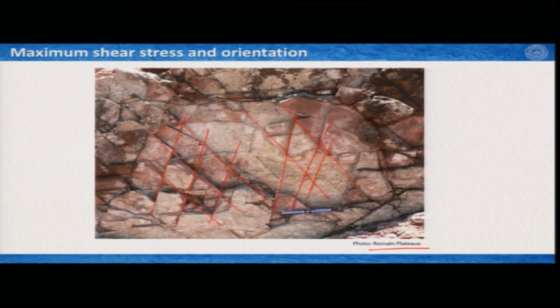Now, it is wise to imagine that these intersection lines, because these are planes, is one of your principal axes of stress, and therefore, if I consider this, these two are your other principal axes of stress. So, I do not know which one it is, but if I consider this one which is projecting upward from the board to be sigma 2, then you can consider this one would be sigma 1 or sigma 3, and this one would be either sigma 3 or sigma 1.